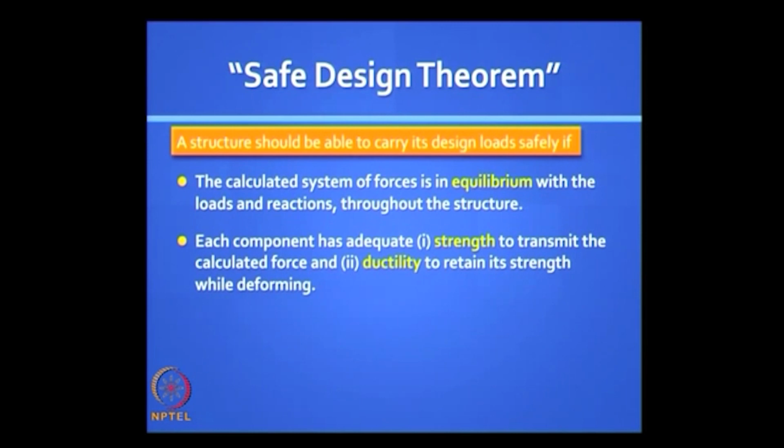Secondly, even if you have nonlinearity in the form of yielding here and there, you have to make sure that the structure remains integrated, that you have possibly the formation of plastic hinges. You studied about plastic hinges, and you must have enough plastic rotation capacity so that the hinges hang on, and that is related to ductility.